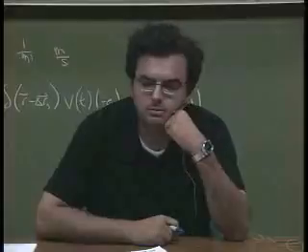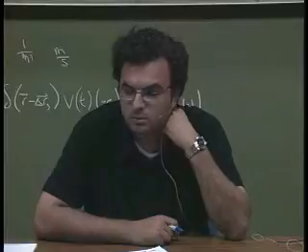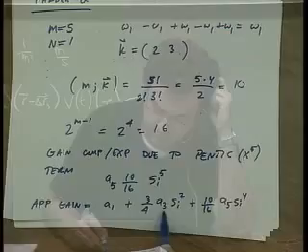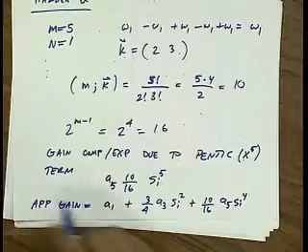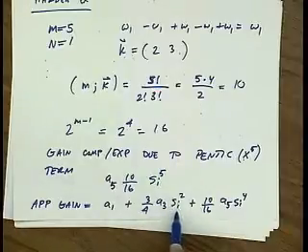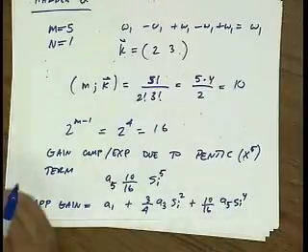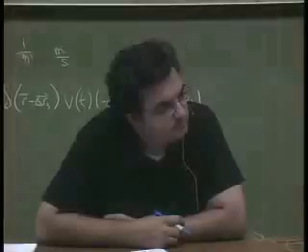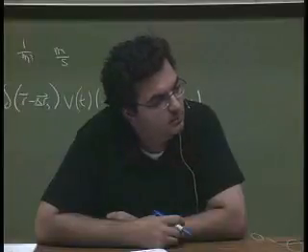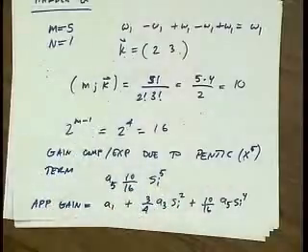Can you use the mic? How would you get a minus term in this if you were to get gain compression? So the sign of A3 and A5 are not known, right? They could be negative. Good point. You'll notice that once you know the sign, the gain compression or expansion is independent of the signal level because you're taking even powers. So, question. If you add the contribution of the complex conjugate, do you multiply the thing by 2? We already did that, right? We already took that into account. That's why we have 2 to the m minus 1. Yeah. All right. Good question.